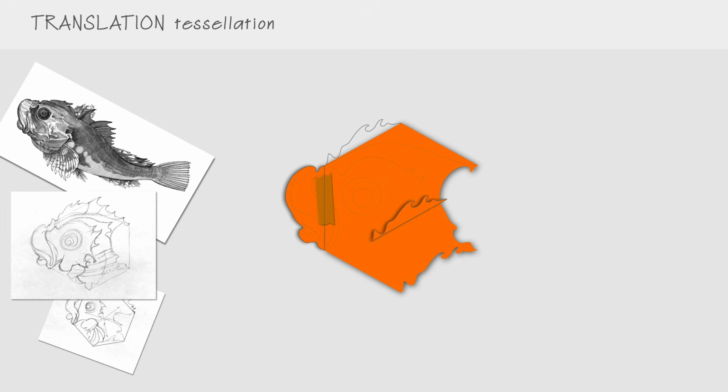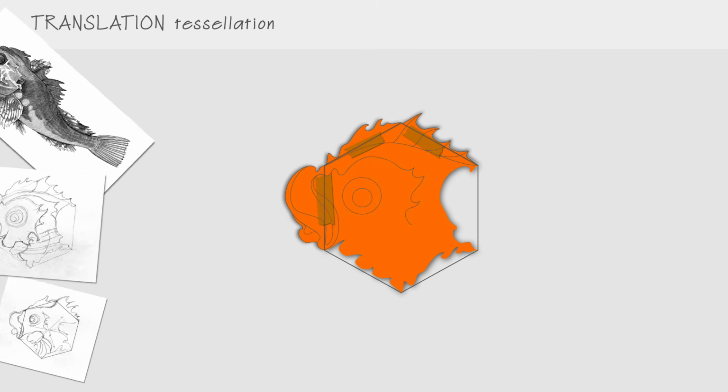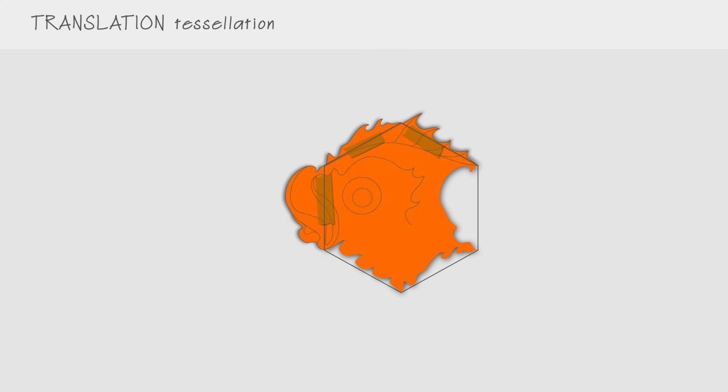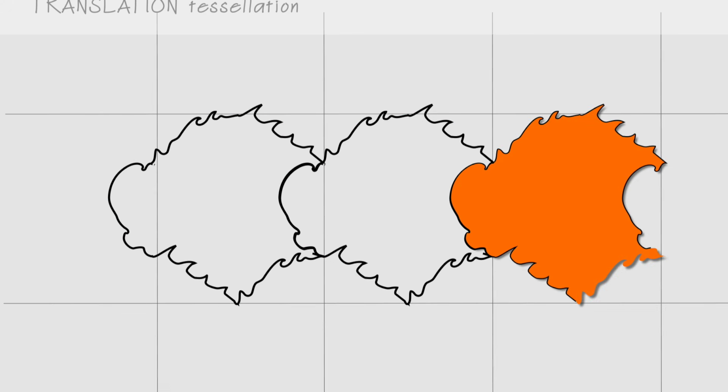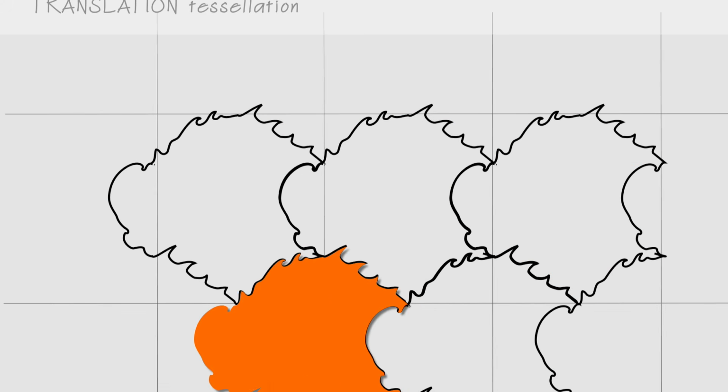And the opposite side is the one that is parallel. Same here. To extend the fin onto this side, use the opposite side to cut it from. Use corner points as start and finish points of the cutting line. This will make the alignment very easy. Use grid for alignment when you trace the tile.